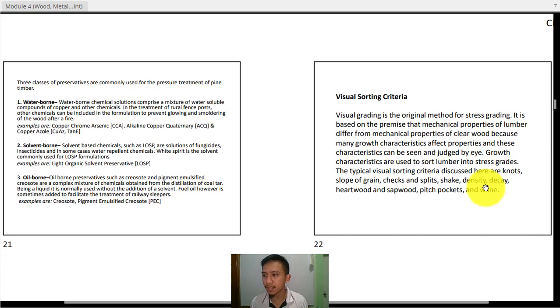Even if you tested one member or one lumber from that group, that will not represent the strength of all of them, since again these woods of different ages, different sizes, and different characteristics have different strength. Therefore, we are not actually doing much testing in woods.